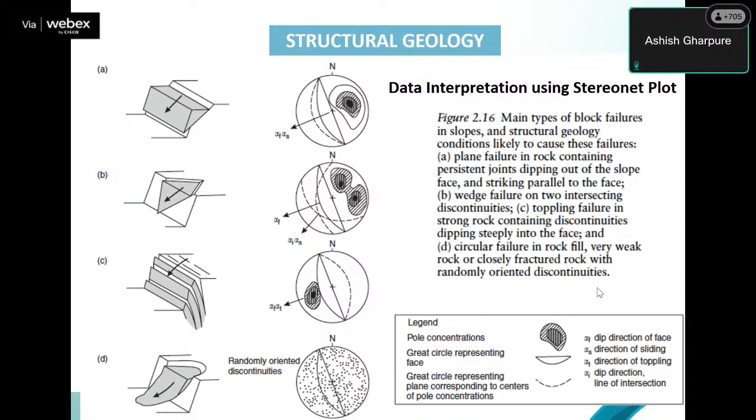If the slope and joint plane are in the same direction, right, then you see a sliding failure. So picture A is a sliding failure. I can't explain the stereonet all in this, but basically, on the outer periphery, if the line is there, that means a flat slope. And if the line is cutting through the center of the circle, that means it's a vertical slope. And the rest is in between, 0 to 90-degree slopes. So that's how it is plotted.